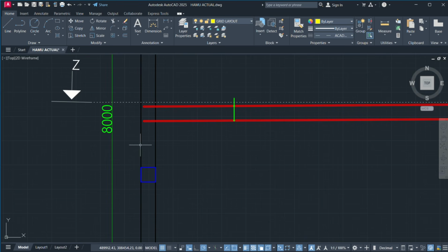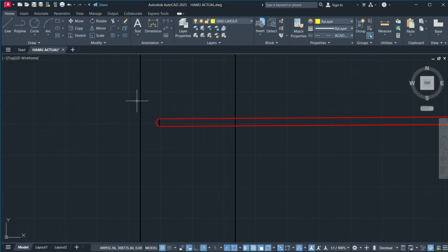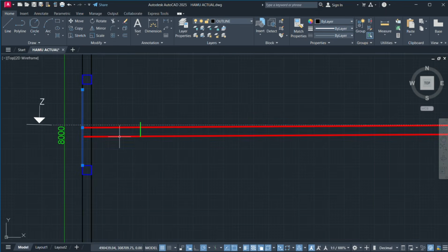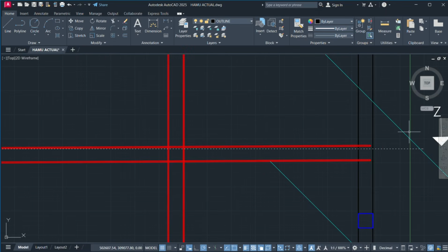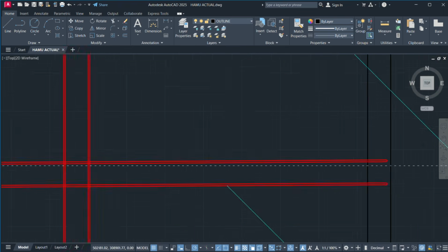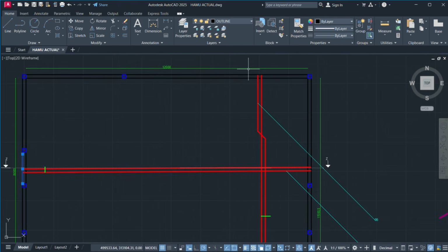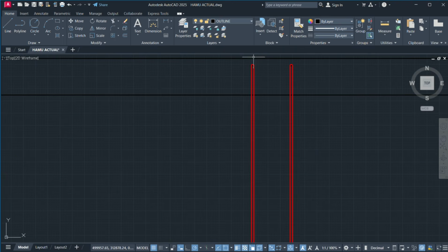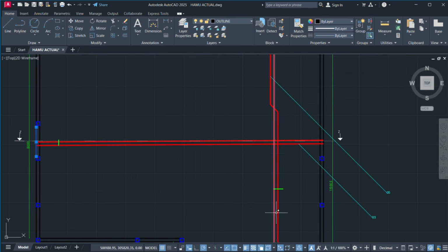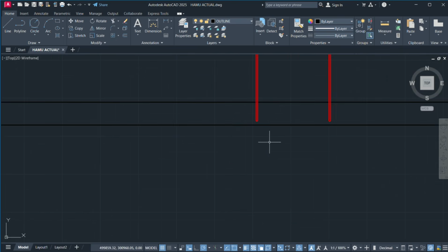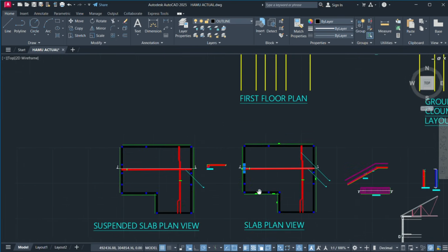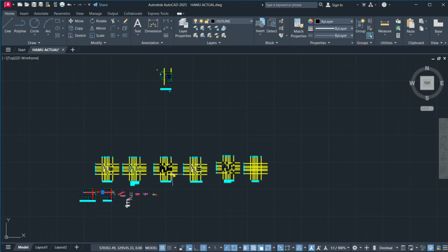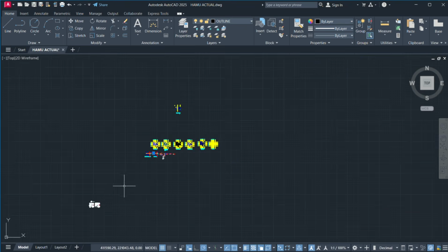For your slab, you're actually going to do a concrete cover of 40. That will be starting from the exterior line, not from the interior line, but this exterior line, you do your 50. Then you're going to have bars that are running all the way. Even this side, you do your concrete cover of 50. Then the bars end where 50 is ending, which is here. Then you also do the same thing this side. You're going to have a 50 here. Then these are going to run all the way down up to here, just like this.